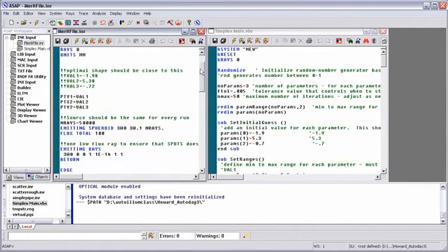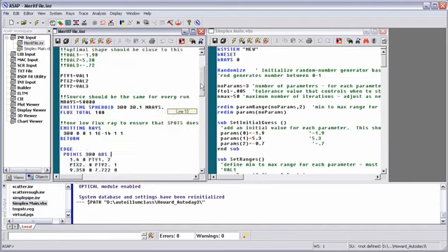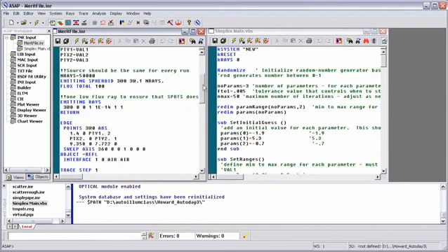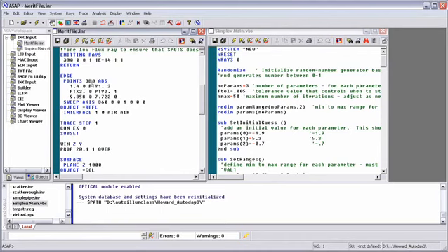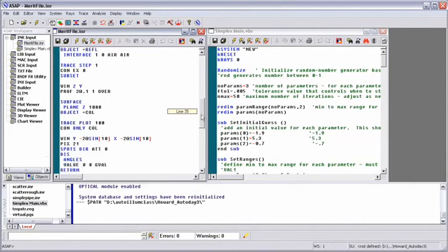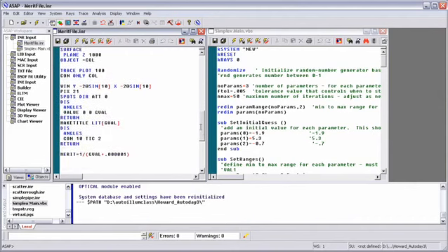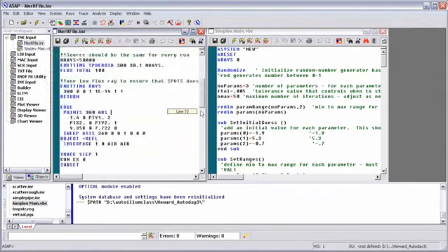So very quickly, what we have in front of us in our ASAP script file is simply a source, and then we're going to build some geometry, and what we've done is we've put in some variables for the points that describe this curve, and then this curve is going to be swept into a reflector. We're going to trace that reflector, and then we'll have a merit value calculated at the bottom. In this case, we're simply going to use the center intensity as the quantity that we want to optimize.